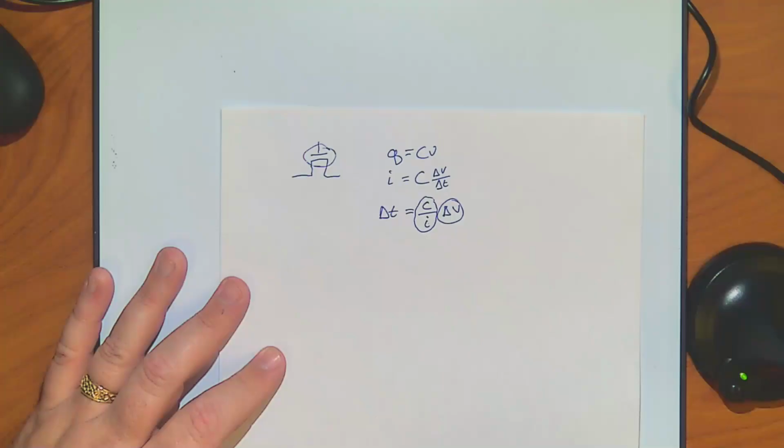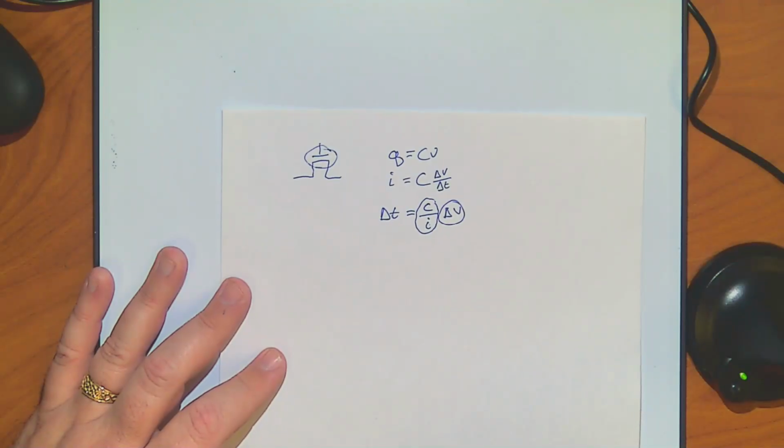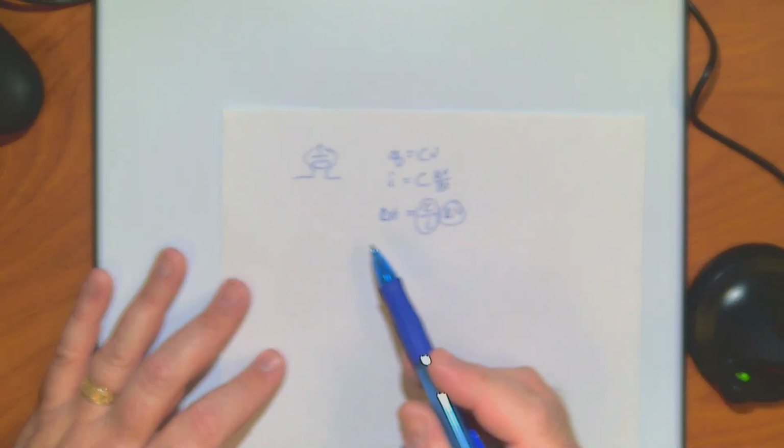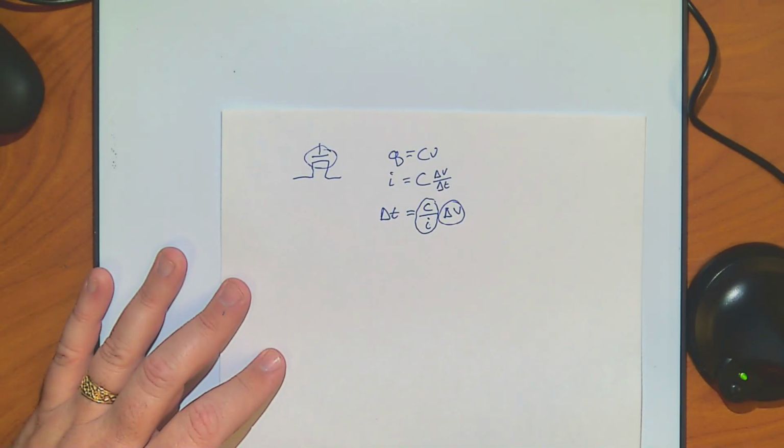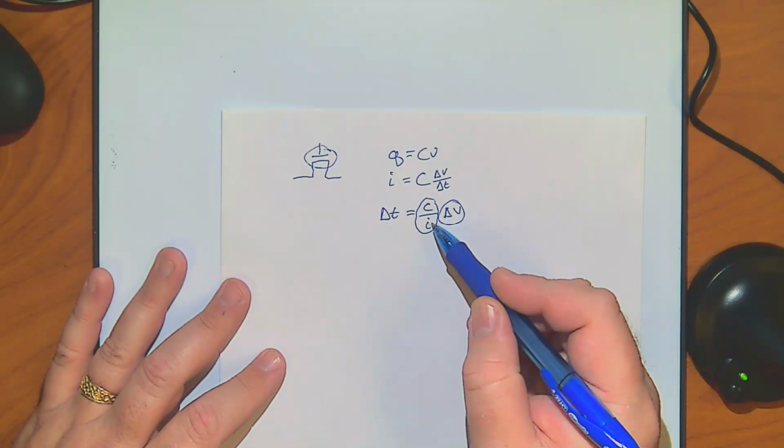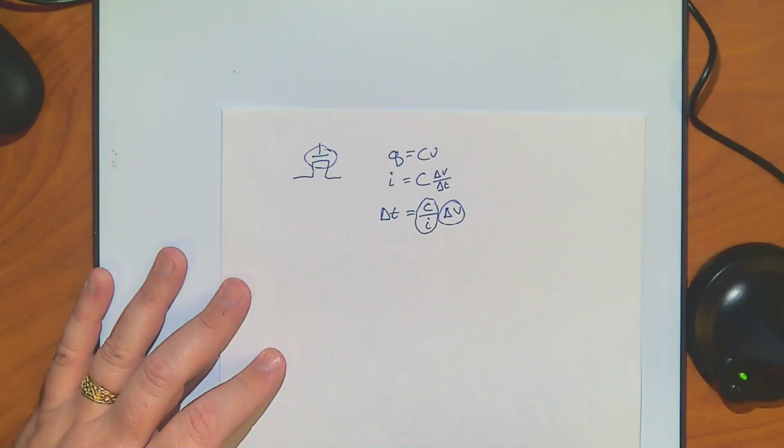Anybody notice the voltages on logic? Well, they keep getting smaller and smaller and smaller. It was 5 volts back in like the 70s and 80s, the good old days, right? And as we moved up, we moved to 3.3 and then 1.8, and it's getting smaller and smaller. One reason is power, but the other is it actually makes it faster. The current, I'd like to give it as much as I can.